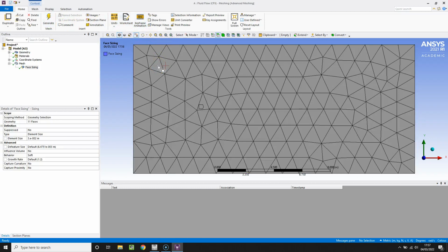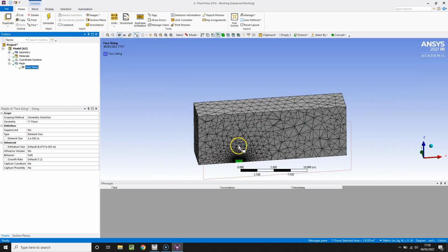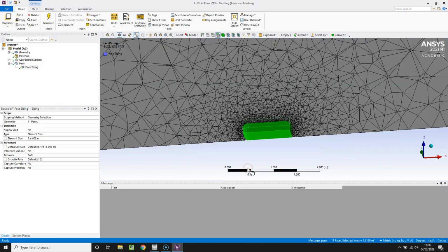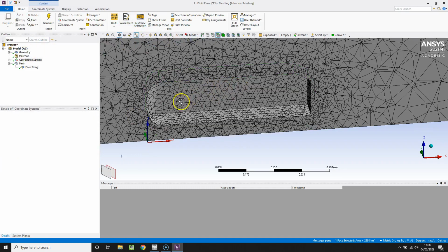And if you're not sure where your Ahmed body is hiding before you make a section plane, just select the region using a box select and then use a section plane. So there we go, we can just cut the vehicle in half and have a little view. And as you can see, we've got our geometry here that's been cut away, and if you just single select elsewhere, what you see is our geometry there.